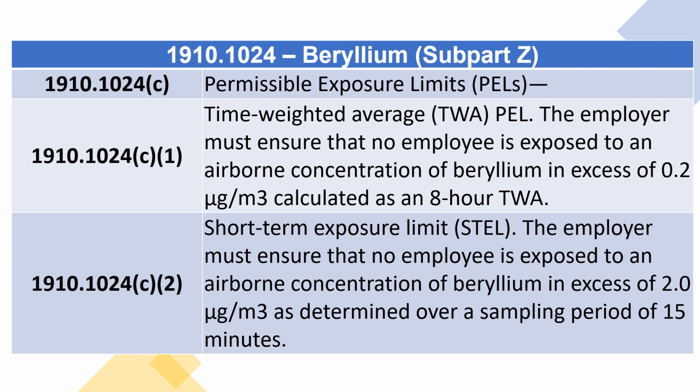1910.1024(c), permissible exposure limits, PELs. 1910.1024(c)(1), time-weighted average, TWA, PEL. The employer must ensure that no employee is exposed to an airborne concentration of beryllium in excess of 0.2 μg/m3 calculated as an 8-hour TWA.